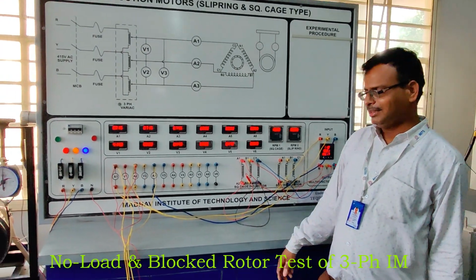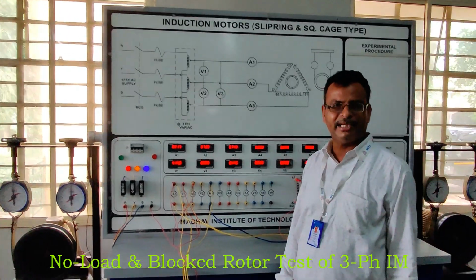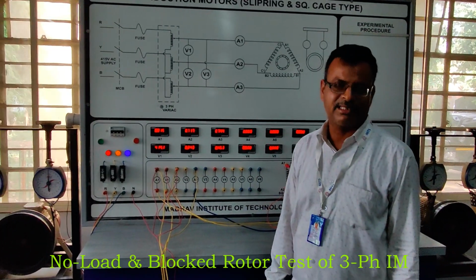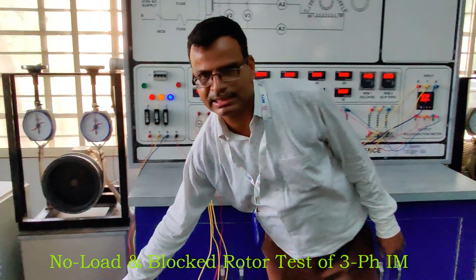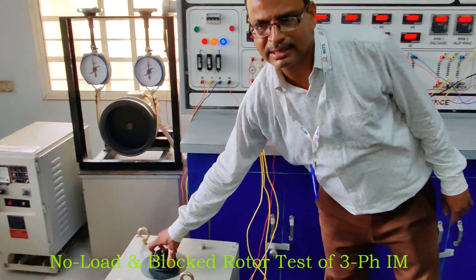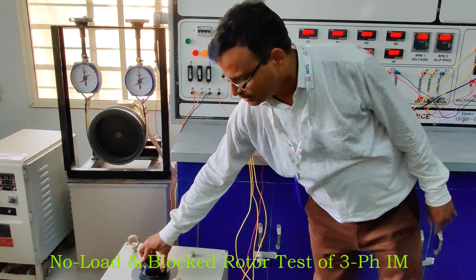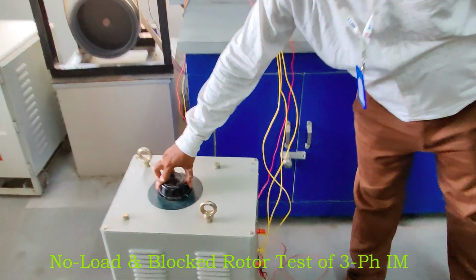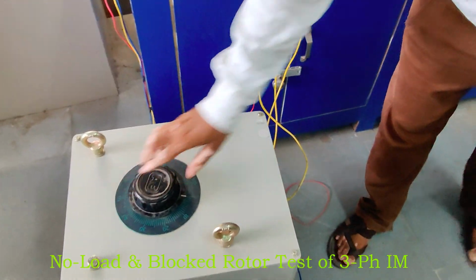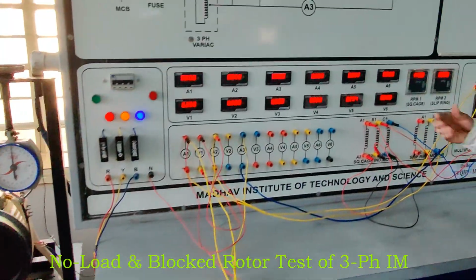Clear? Now for the second test, the block rotor test. In the block rotor test, firstly we will reduce the voltage and bring the auto transformer knob to 0 position, and the speed gradually slows.